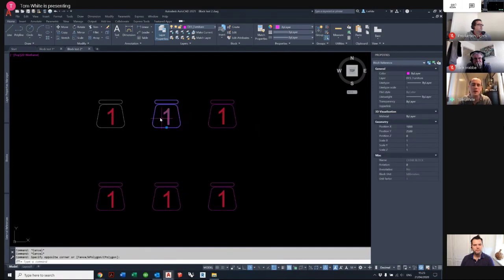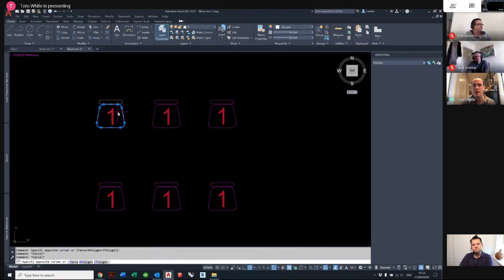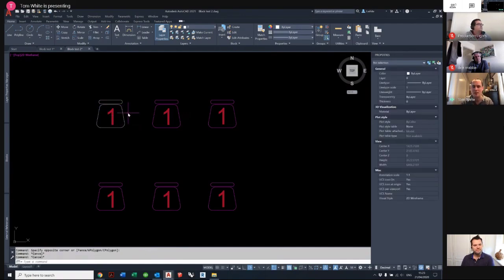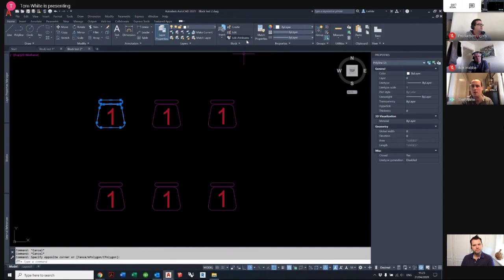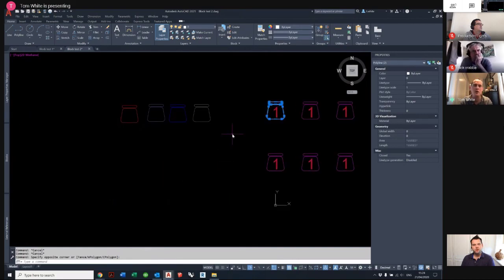So moving on to this one here. These 3 elements have used the set by layer, and so when you've run that command, it has forced whatever layer the element was on to go on to what layer? The current layer, or something that you've specified, or what? The actual layer name stays the same. It's in the top ribbon up here. You can see there's a color symbol, there's a thickness symbol. So it's actually the properties that are being set by the layer properties, is that correct? That's entirely correct. Gotcha, which is cool.